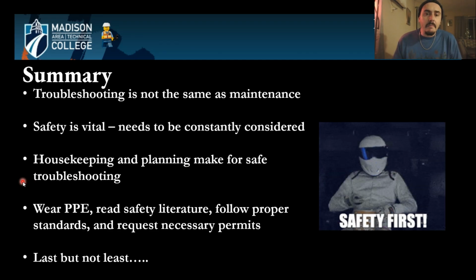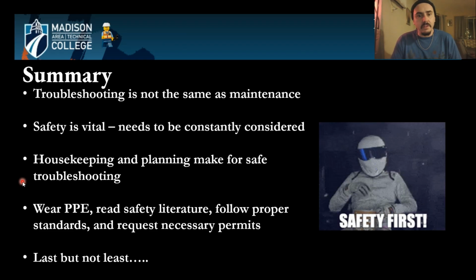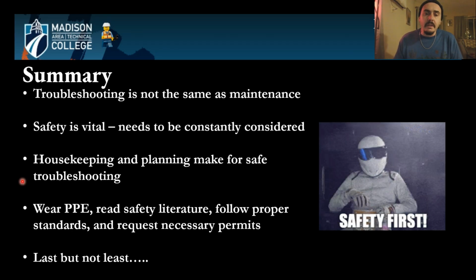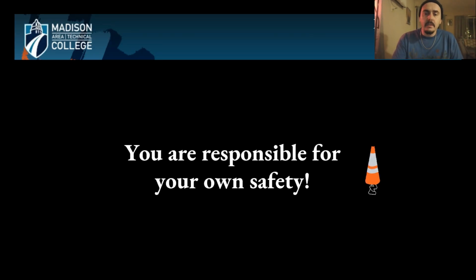Housekeeping and planning make for safe troubleshooting, so keeping everything in order and following a methodical process will keep you safe while you're troubleshooting. Wear any PPE, read all the literature, follow the proper standards, and request any necessary permits when troubleshooting. And last but not least, you are indeed responsible for your own safety.